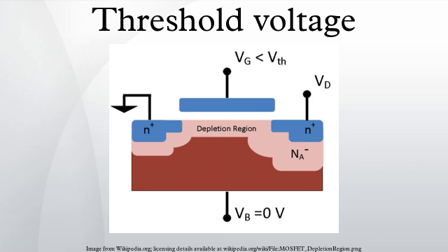Body effect. The body effect refers to the changes in the threshold voltage by the change in the source-bulk voltage. Because the body influences the threshold voltage, it can be thought of as a second gate, and is sometimes referred to as the backgate. The body effect is sometimes called the backgate effect. For an enhancement mode NMOS MOSFET, the body effect upon threshold voltage is computed according to the Shichman-Hodges model using the following equation.